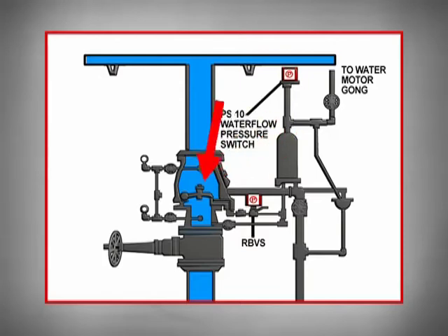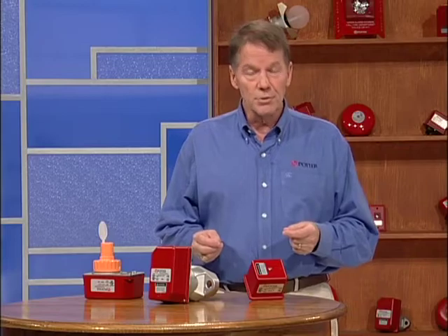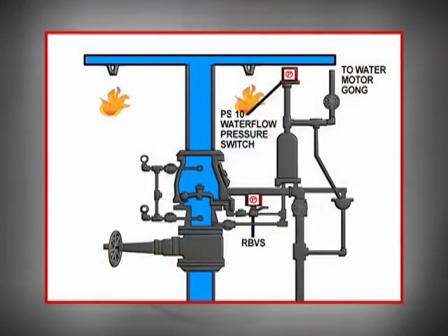An external or internal bypass reduces the possibility of false alarms under low flow conditions. When the water supply pressure exceeds the sprinkler system water pressure due to a sprinkler opening or a surge in the supply water pressure, the valve opens and the alarm port is exposed to incoming water.